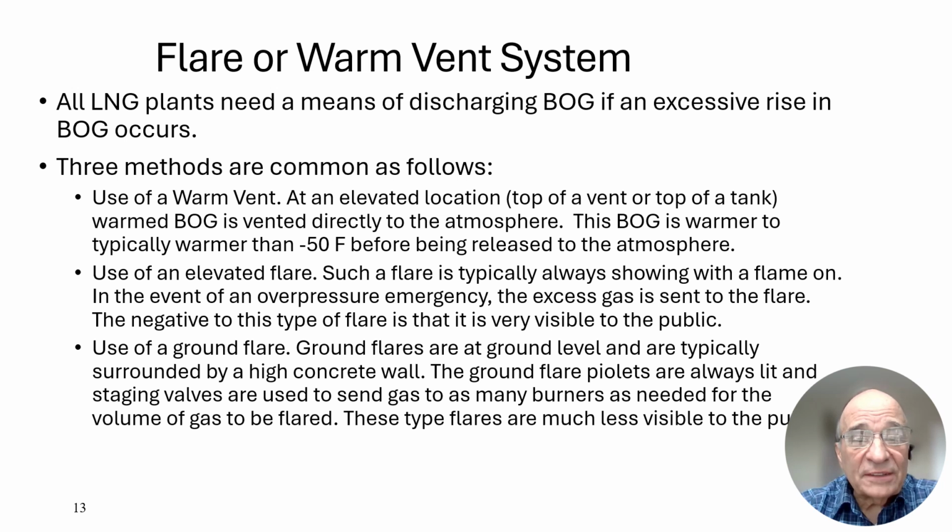Flare or warm vent systems. If there's excess gas in the plant that needs to be relieved to the atmosphere, it is typically sent to a flare where it is burned and therefore made safe. Once it's burned, it produces CO2 and water vapor.